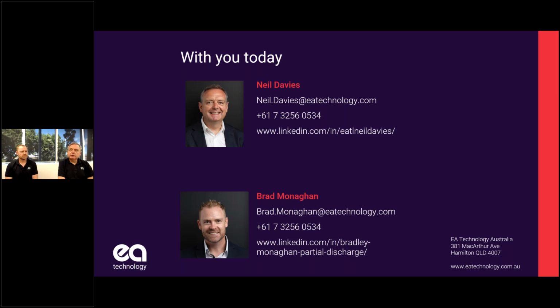If you are going to do VLF type testing, so stress or high pot testing of cables when you're commissioning, then we would always strongly recommend that a proper PD test is done rather than just a withstand test. A withstand test is not realistically going to find you any underlying defects in quality workmanship of joints and things like that. So I think that first year or so of its life it's important.